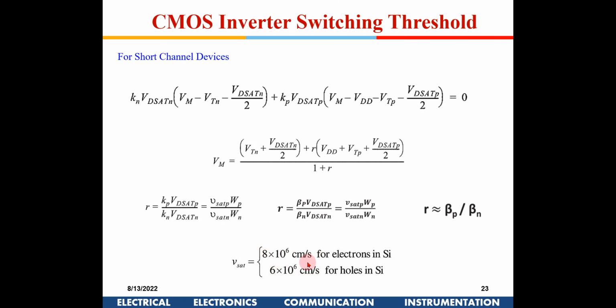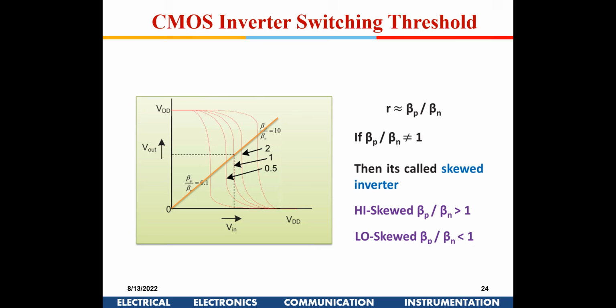But for a 180 nanometer technology and all, for all our designs which we are going to do in LTSpice, you have to keep PMOS 2.5 times. Okay, even that 2.5 times will get modified in the next slide. Okay, let me show you that. So this is like for a short channel device.